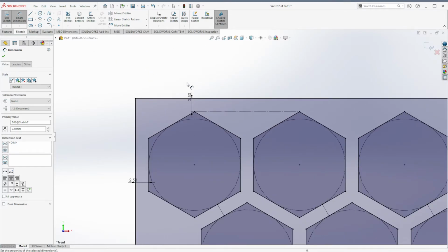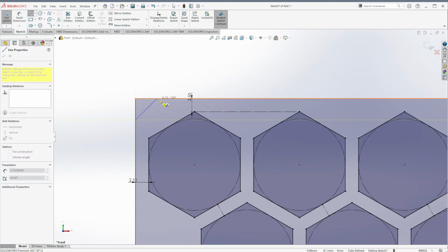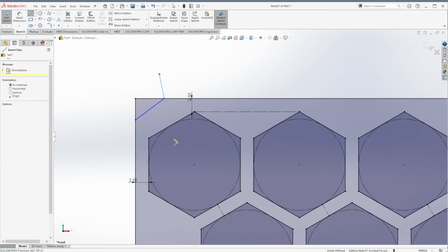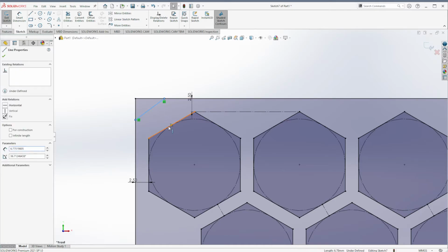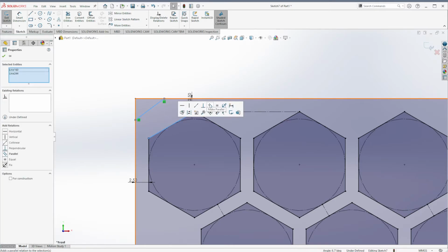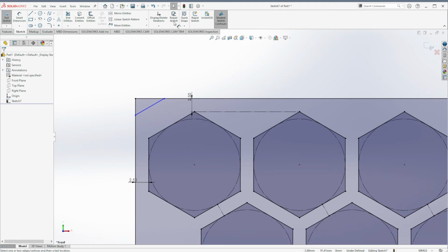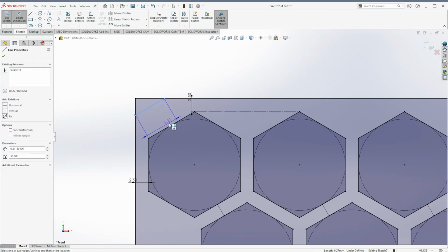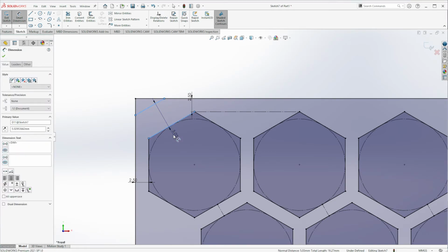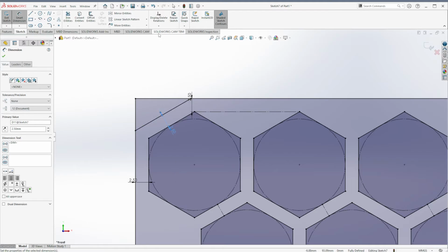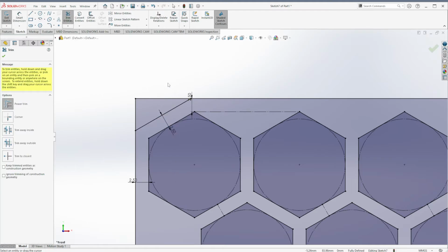I will show you one. We'll just cut out this corner as an example so you can extrapolate from it. We're going to draw a line like this, make it parallel to the hexagon here, and give it an offset of 2.5 millimeters, which is our material thickness. And then with the trim tool, you can just slice through a corner like that.